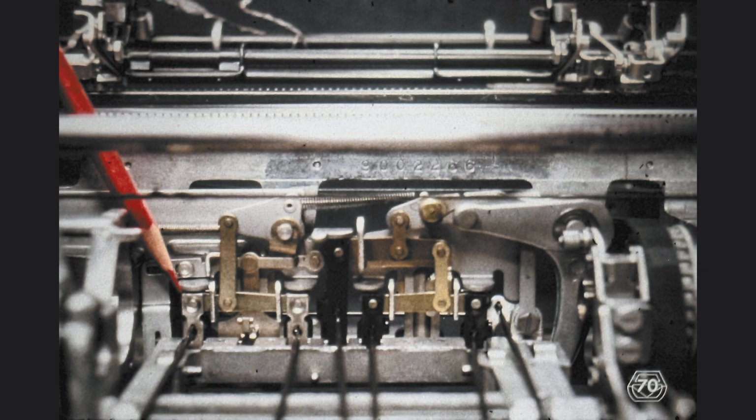At this point, you should hand cycle the degree mark or an exclamation mark and observe that because we pulled down the indicated tilt 2 latch, we obtain 2 tilt increments of rotation for the type element. See if you can provide the explanation which justifies this result. Pause here if necessary. Your explanation should have sounded somewhat like this.